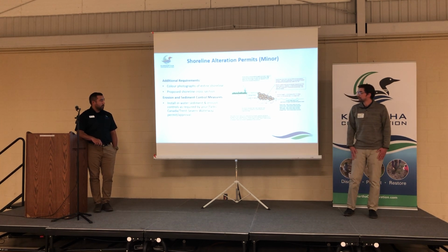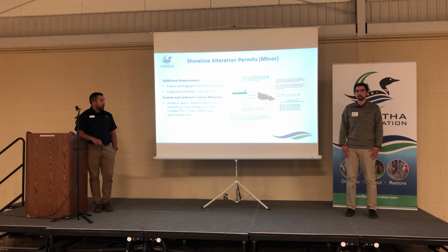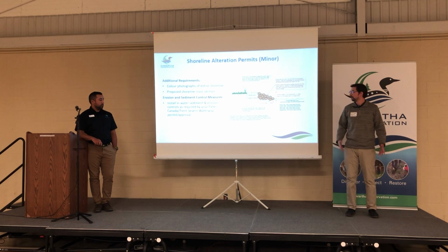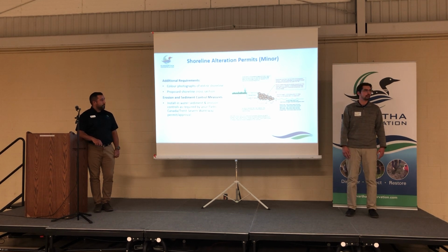In terms of erosion and sediment control measures for shoreline alteration permits, they do vary. Generally, if you're in the Kawartha Conservation watershed, you would need a permit from Parks Canada or Trent-Severn Waterway, and we would work with you to use those requirements that they would give to your proposal and include that as a condition on our permit. Generally, that could be things like turbidity curtains, silt fencing, etc. And we may also request that additional on-land measures are installed as well, assessed on a case-by-case basis.